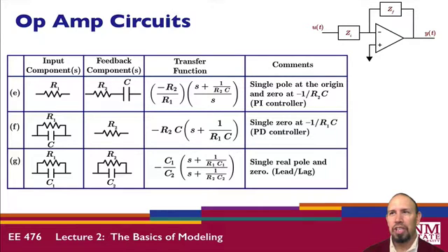The analog computer is a connection of R's and C's and op-amps that can be used to simulate the differential equations and the trajectories they needed for the moon trajectories and so forth. So op-amp circuits are very useful that way, and these are some of the basic uses for a single stage of op-amps like this.